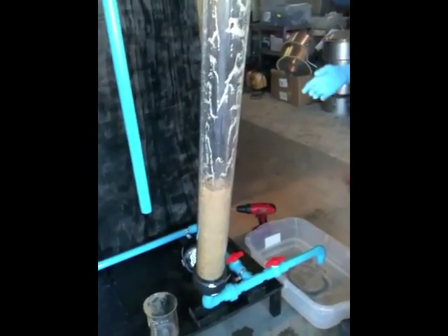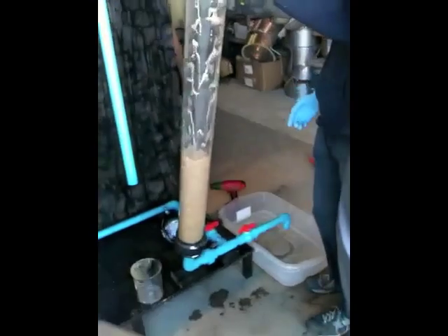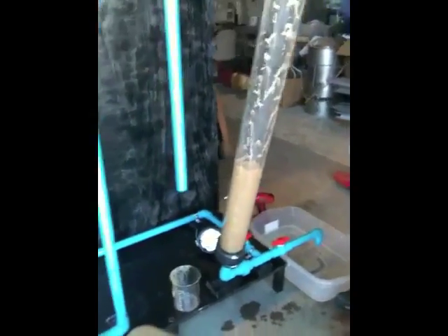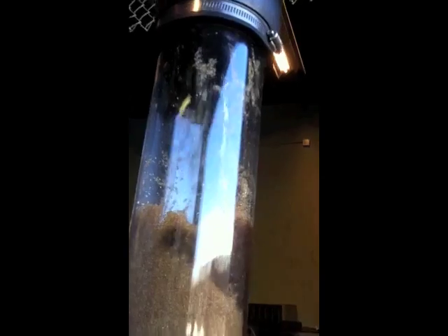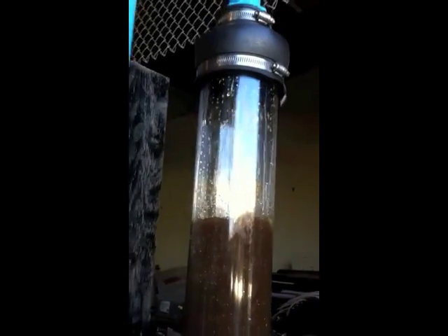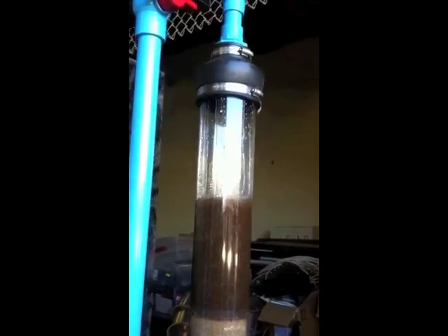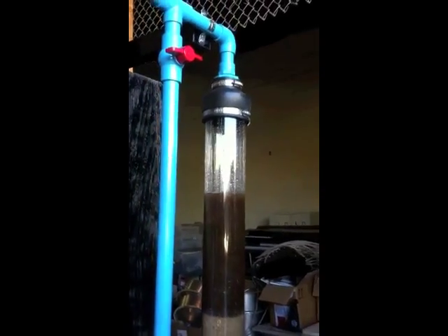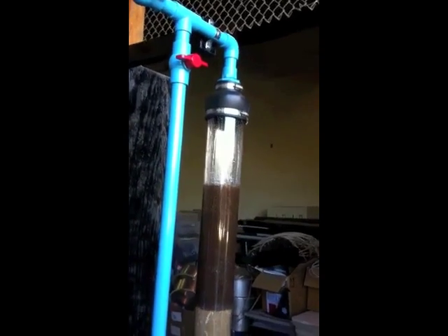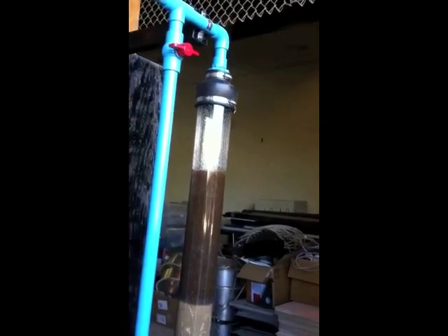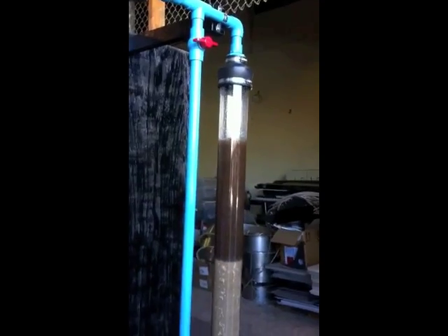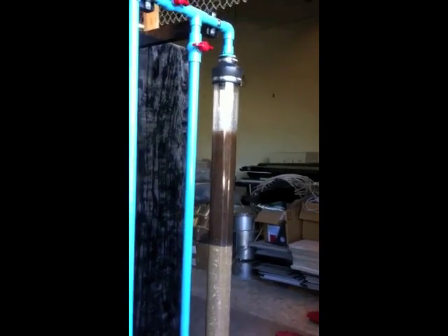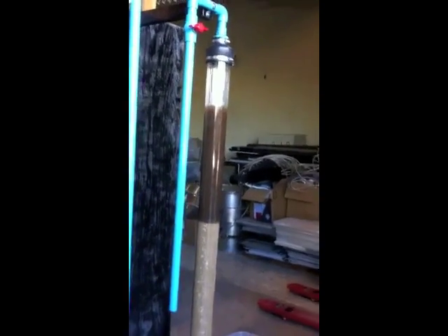The 9126, the cation resin, has a minimum capacity of 1.9 equivalents per liter, a moisture retention of 49 to 54%, a diameter size of about 610 micrometers, and a specific gravity of 1.21. The difference in specific gravity allows the bed to separate completely during backwashing. The anion resin will float to the top and the cation resin will sink to the bottom. This ensures that the 2 resins will not be cross-contaminated by the chemicals used in the regenerative process.